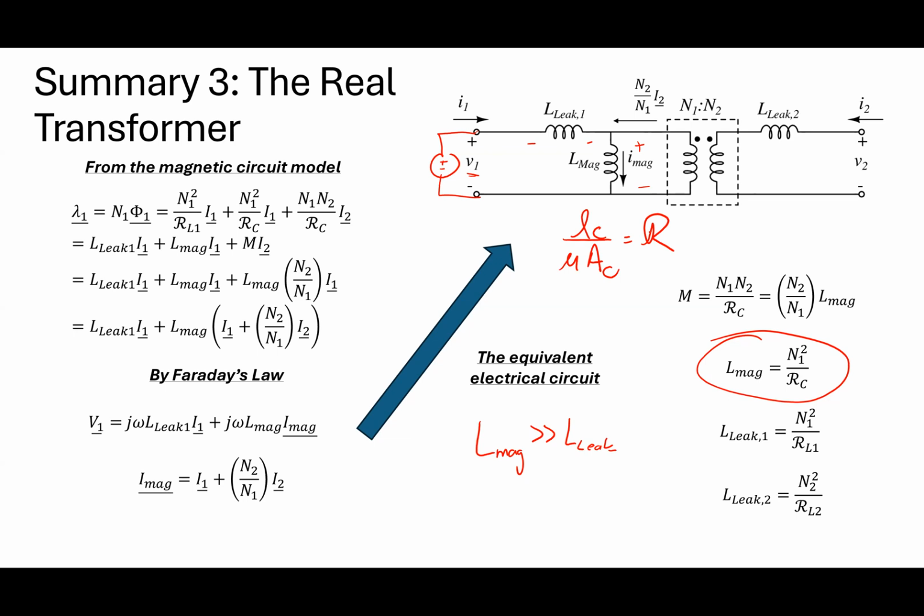In general, the reluctance of the core would be the combination of all the elements of the core. If I think of that magnetic circuit as just a resistive circuit, the core reluctance is the equivalent resistance combining all of them. Usually you can reduce that down to one number.